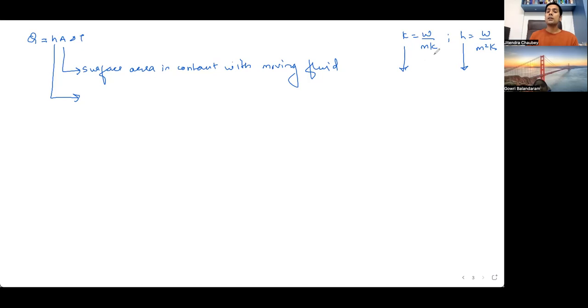Do you understand this terminology, Kelvin? In heat transfer, never try to convert Kelvin to degree or degree to Kelvin. In other subjects like thermodynamics or refrigeration and air conditioning, or where temperatures have powers, like in the radiation chapter, you might have to take care of Kelvin.